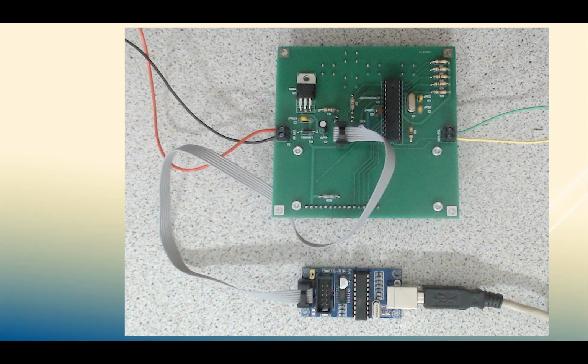This is the back side of the new EasyBus master that I showed you earlier. So I'm programming that directly. The benefit of this method is it doesn't need a bootloader. In other words, you can recover that 2K. If you're short of memory, you can recover it. Don't use the bootloader, don't use the USB, but use the tiny ISP.